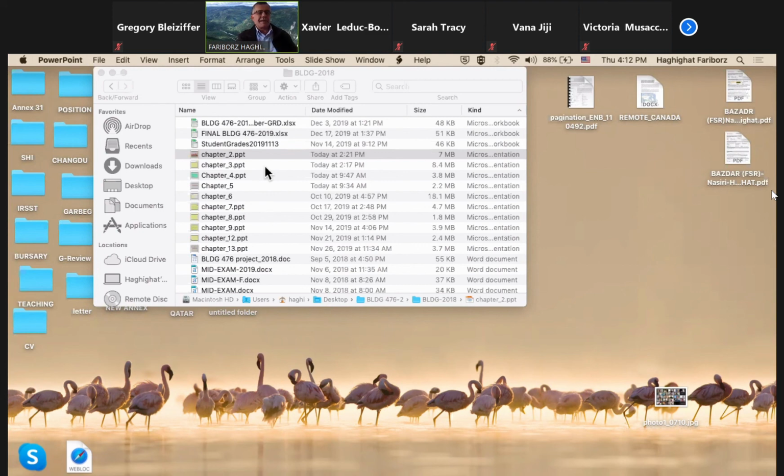Therefore, it becomes k of the soil times (T floor minus T at 5 meters down) divided by 5 meters, plus the convective heat transfer coefficient between room air and the floor, plus Q coming to that point. How much Q comes is equal to the solar energy through that window times the area of the window times tau times alpha. Remember, the area is now different.